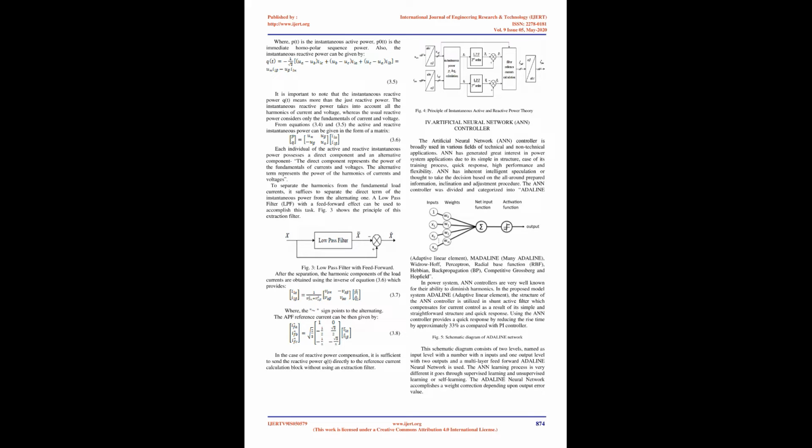The idea of utilizing active power filters to alleviate harmonic problems and to compensate reactive power was introduced over 2 decades back. It has demonstrated its capability to regulate the network current and to improve the quality of the power. The theories and applications of active power filters have become progressively popular and have attracted great attention. Without the downsides of passive harmonic filters, such as component aging and resonance problems, the APF appears to be a feasible answer to compensate for reactive power and eliminate harmonic currents. As we stated earlier, SAPF is connected in shunt with the nonlinear load to act like another controlled nonlinear load.